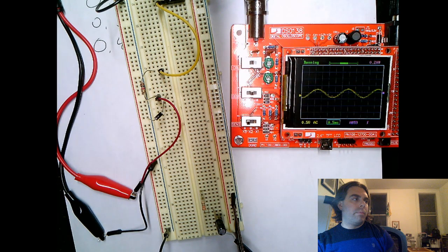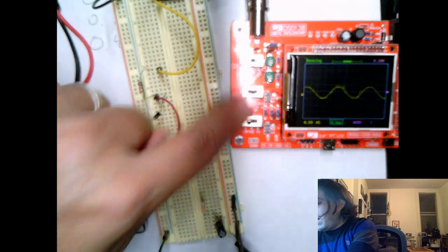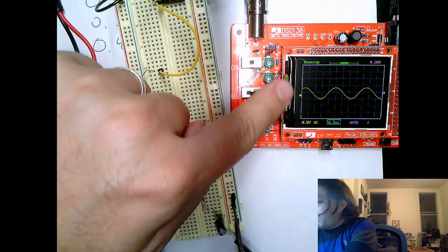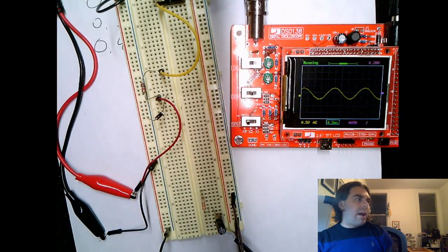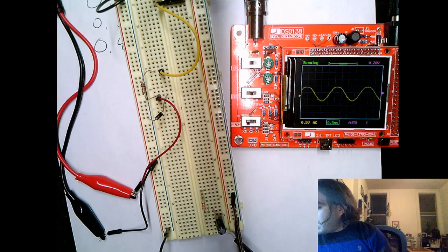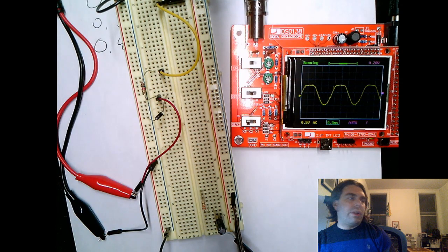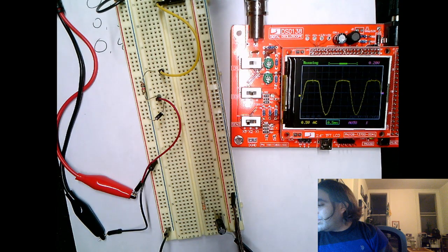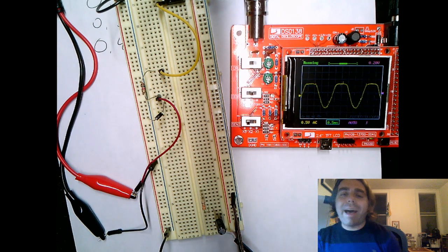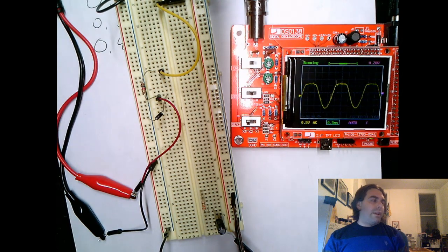So now I'm on 0.1 and x5. So all of these divisions are 0.5. So basically, I have a sine wave, but as I increase the volume, when it hits like the first line, it starts to kind of flatten out, right? And as I increase the volume, that flat line remains at about the same level, even as the volume goes up, right? So what's happening?